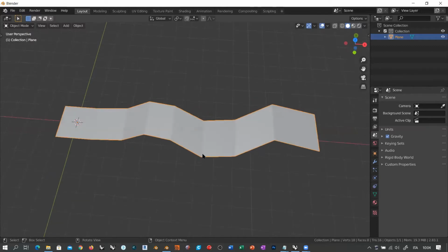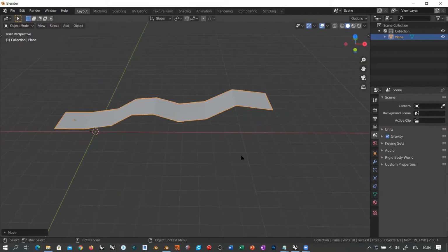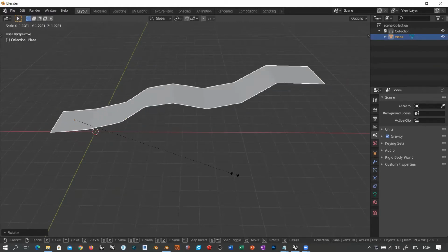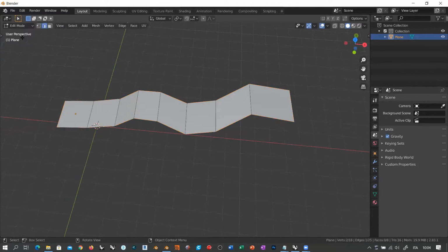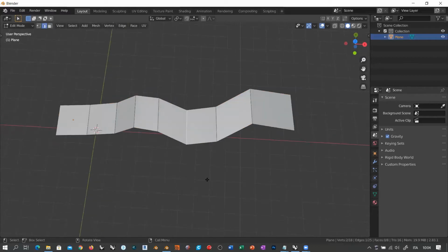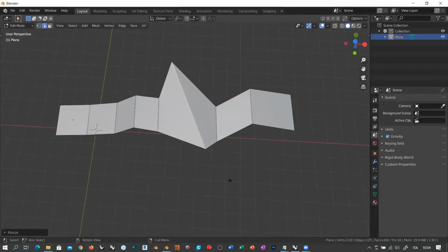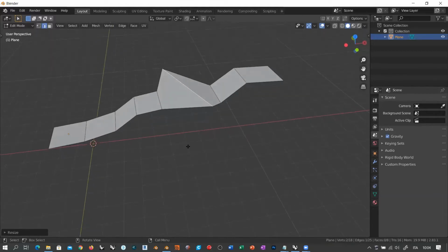I can do a global transformation like G, moving the whole object, R, rotating the whole object, S, scaling the whole object. You know. But if I go back into edit mode, I can, for example, select one topological element and move it, rotate it, and scale it. So topological editing allows us to define the mesh properties according to its original elements. Okay.